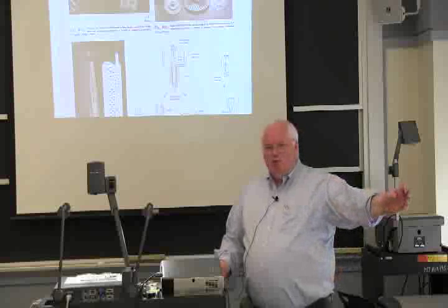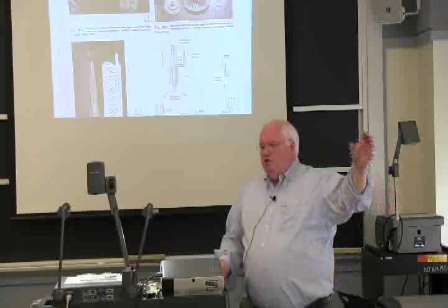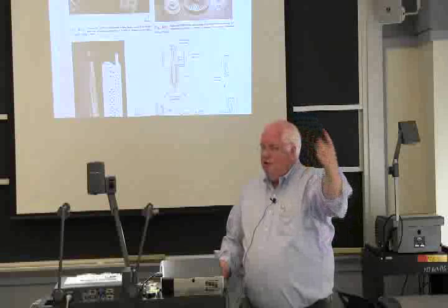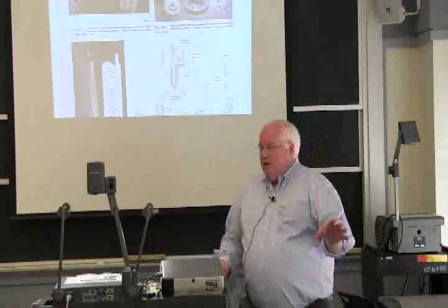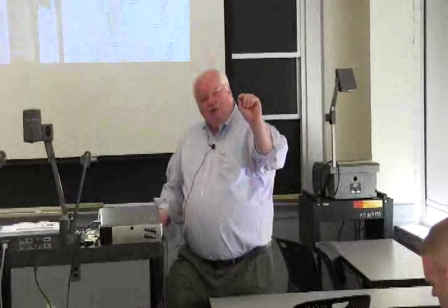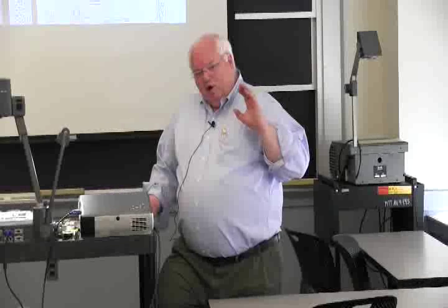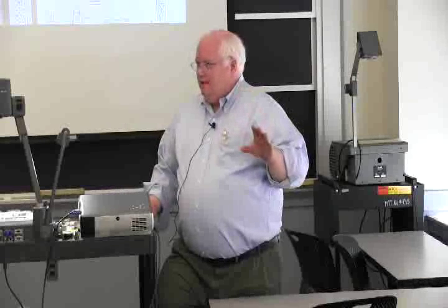You put one of those blades in there after you cast it, and you get a full three-dimensional image, inside and outside, just like doing a CAT scan on your brain or on your arm. Only it's designed for metals. And they do a 100% CAT scan. They measure the wall thickness on that CAT scan, and they probably scrap, hopefully, less than 30% of the production, okay?